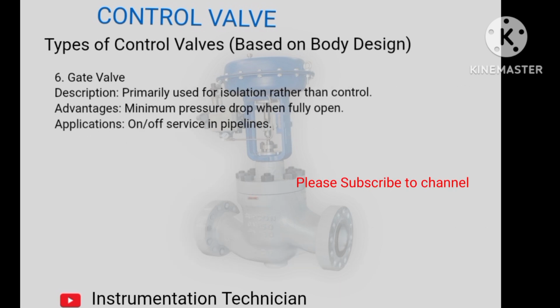6. Gate valve. Description: primarily used for isolation rather than control. Advantages: minimum pressure drop when fully open. Applications: on-off service in pipelines.